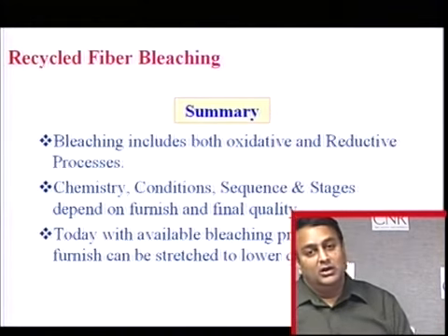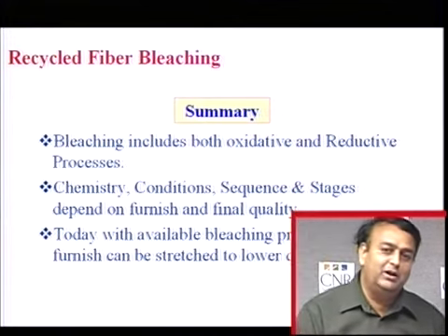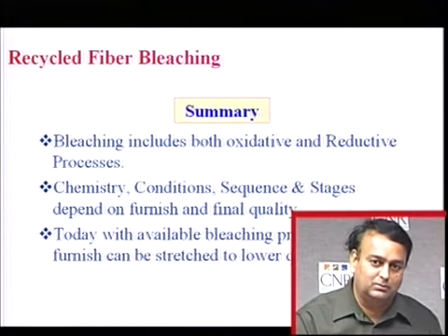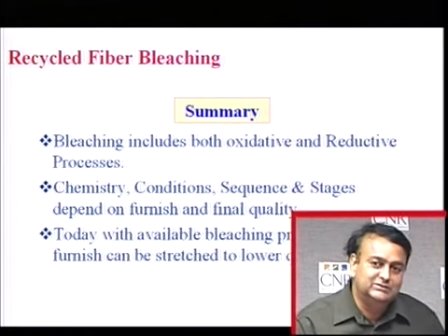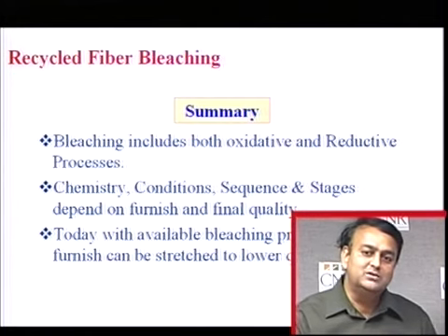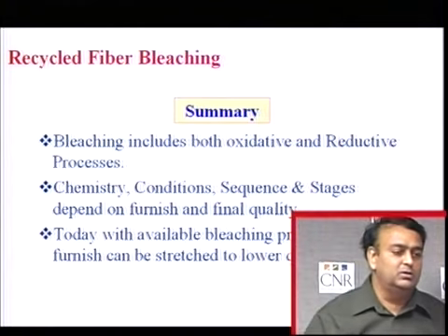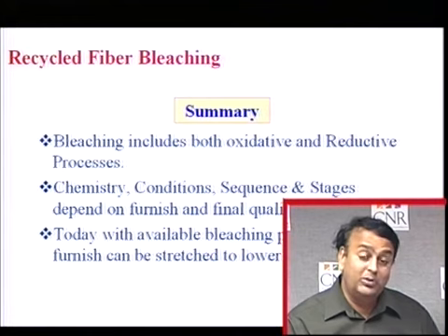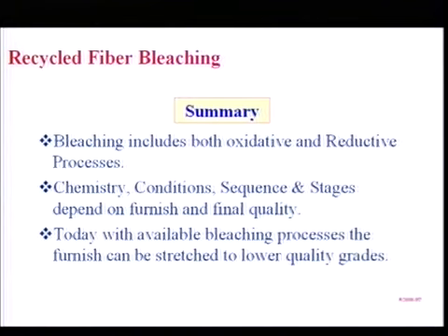In summary, recycled fiber bleaching is exciting because it contains chemical fiber, it contains mechanical fiber, it contains brown fiber, it contains once bleached fiber. That is why it is called recycled fiber. It also contains dyes, ink, fillers, fluorescent whitening agents. All these compounds present in your fiber can make your bleaching challenging. So, what do we need? We need multi-stage bleaching to take care of all these compounds. Oxidative and reductive bleaching processes are very useful.